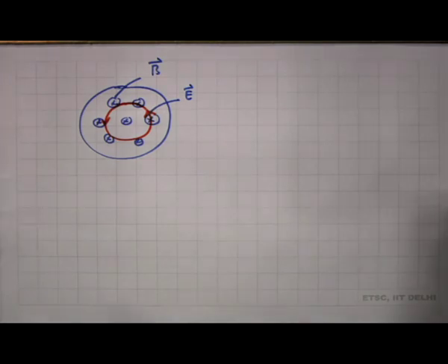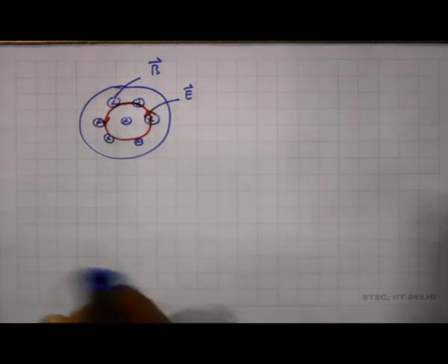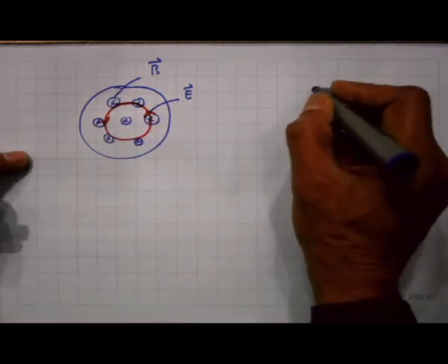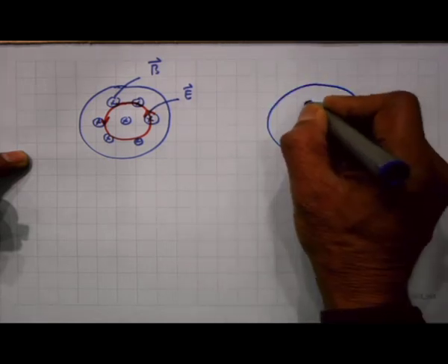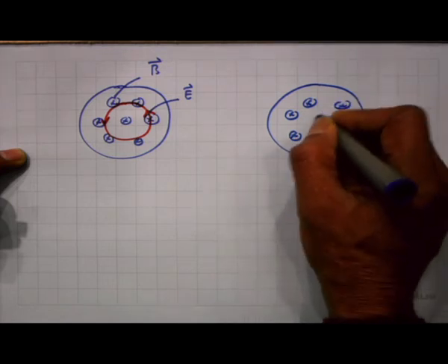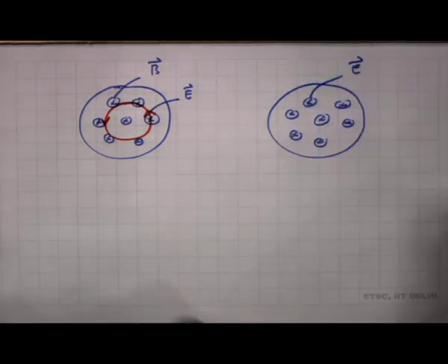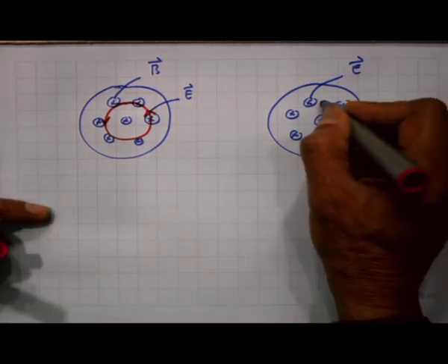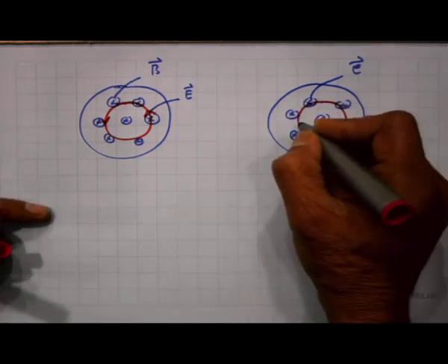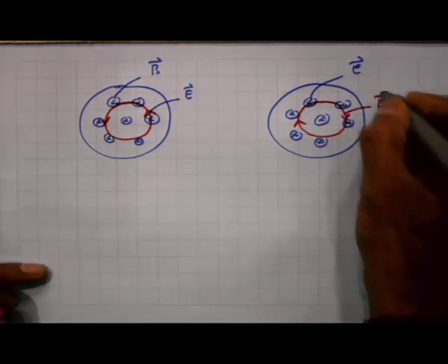So, if the magnetic flux is increasing with time pointing downward, because of the negative sign here, the induced electric field will be in this direction to oppose the change in the magnetic field. If I take a corresponding problem and if I had electric field pointing downward, and the electric field was changing with time, and if I take another loop like this, the direction of induced magnetic field will be like this. So, that is the magnetic field, sorry, this is magnetic field.